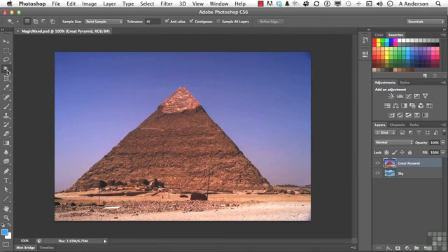But what we can do now, which is really cool, is change it right here. I'm not usually a big fan of selecting one tiny pixel. Usually I go about 3 by 3. If I'm going to flesh tones, I might be about 5 by 5. It just depends on what you're trying to do. So let's go into 3 by 3 average. It gives us a little bit more of a sample.